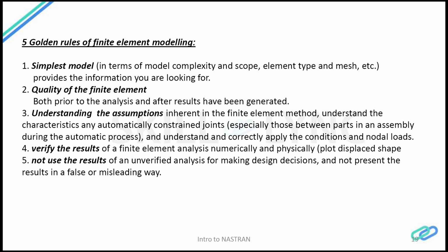And then understanding the assumptions, as I mentioned. One has to understand the assumptions, especially in terms of the attachment areas and the constraint areas, and then finally verifying the results. The results should verify whatever numbers the FE tools throw back.